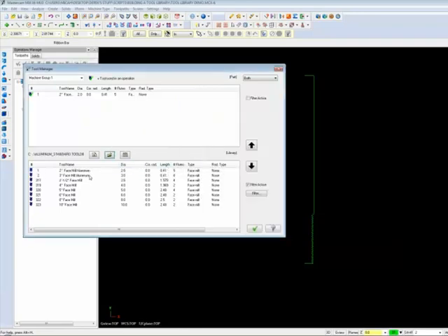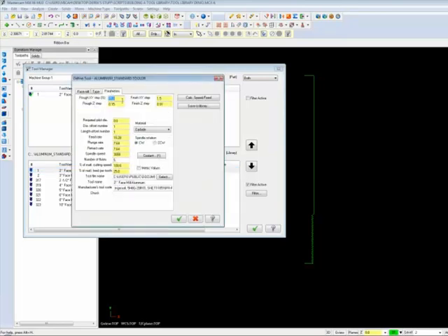You going to comment on that, Jay, or else I'll comment on that one? Go ahead. Mike, what you really have to watch for, and this is how you can really make scrap fast, is using that shell mill definition. In my opinion, it can get real dangerous, because it's using the bottom diameter as the cut diameter.